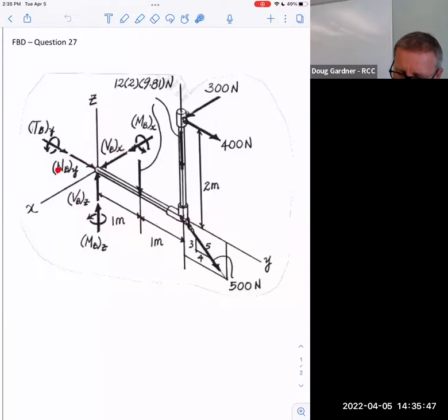Except, no, he called it normal, not shear. Notice that's interesting. I kind of got in a hurry. He called it normal. At first I thought he made a mistake, but isn't that in the direction of the axis that the pipe happens to be? So instead of calling it shear, because that's not going to be shear, shear is this way, normal is this way. So he gave it a totally different name, didn't he? And yet those are all the forces going in those directions. 2 of them are called shear, 1 of them is called normal.